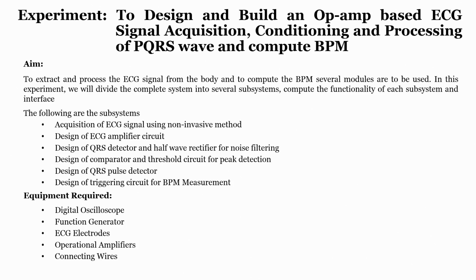So, that means we need to do a differentiation, and moreover, since the signal-to-noise ratio is really poor in the acquisition of a raw ECG signal, we need a proper signal conditioning circuit which can improve the signal-to-noise ratio. We also need a filtering circuit to remove the unwanted signals present in the ECG signal. To remove them, we should understand what the unwanted signals are and why they come into the ECG signal.